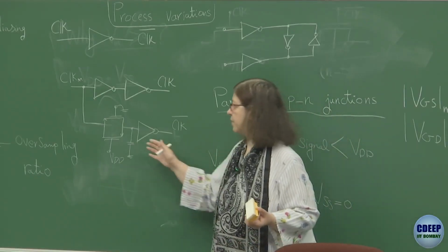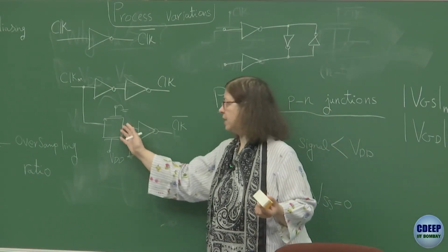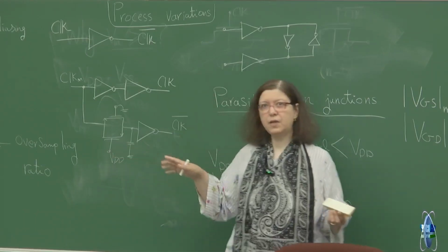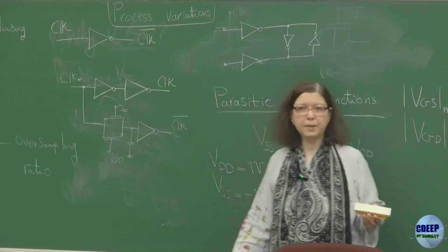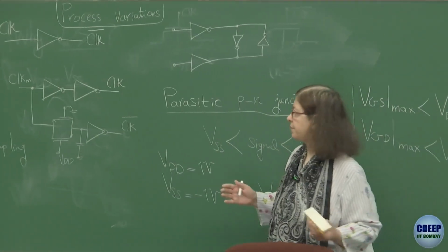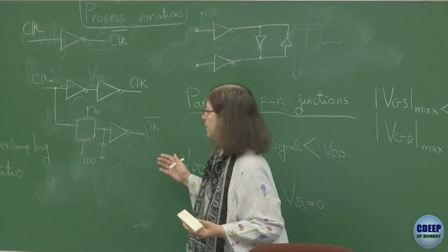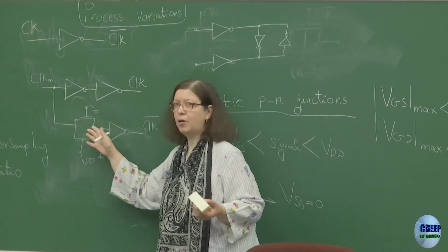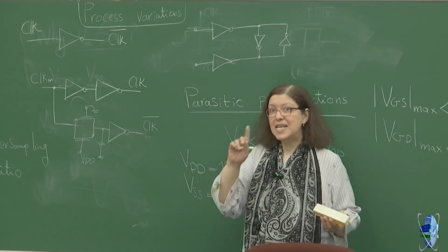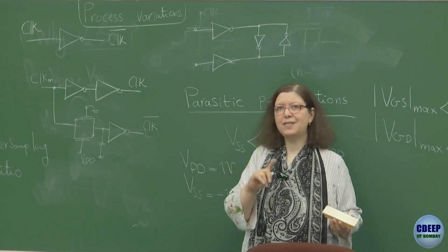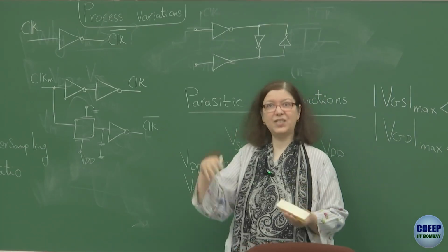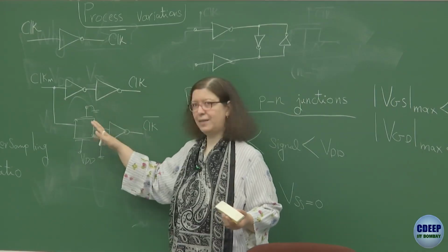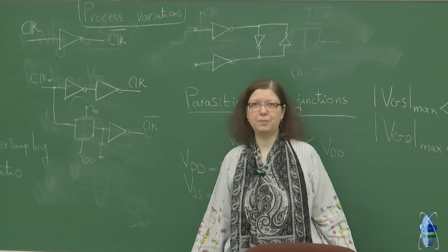It says that, okay, we don't put an inverter, we put a switch which is always on. See, the problem with the switch which is always on and still subject to variation is that here you have tried to compensate one of the inverters with that switch, but this is always a resistor. An inverter actually operates as an amplifier in some range, but with high gain. That's why you are not matching them properly. So that's why this also will have a similar problem.